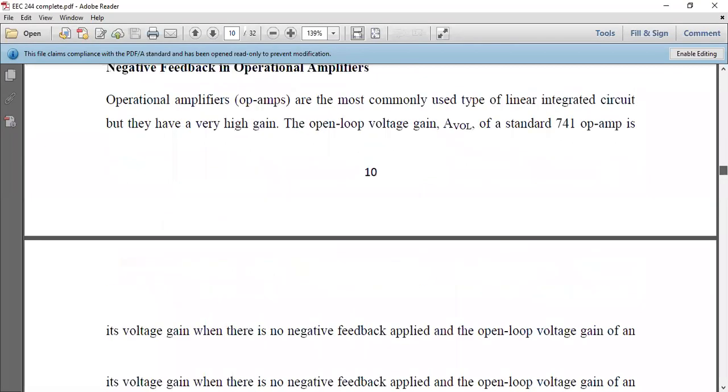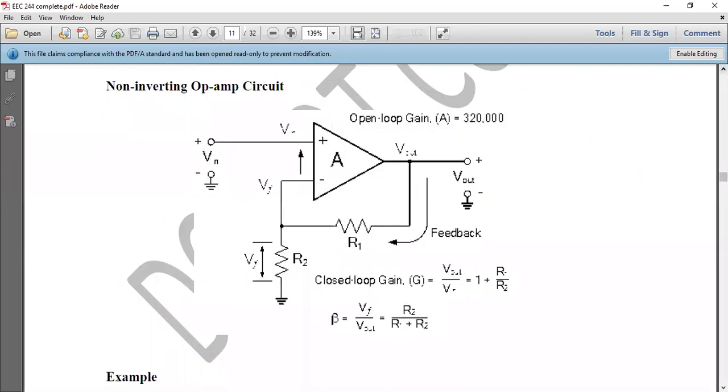So the amplifier is connected as a negative feedback amplifier in that manner. But we need to introduce some circuit elements to ensure this feedback is connected. We don't normally connect the wires directly like we have up there, but we wire it like the example on the screen now. We have the amplifier gain A, which is an operational amplifier, and then we have the non-inverting input terminal plus here, where the input voltage V input is applied.